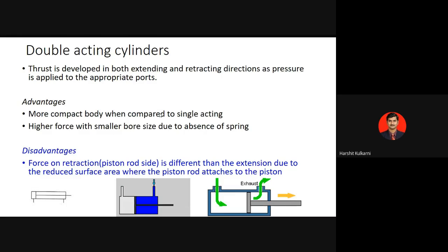So here, in the case of double acting cylinders, you have more thrust applied and a more compact body when compared to single acting. Higher forces with smaller bore size. There is no spring over here, so you can have complete loading during extension as well as retraction.